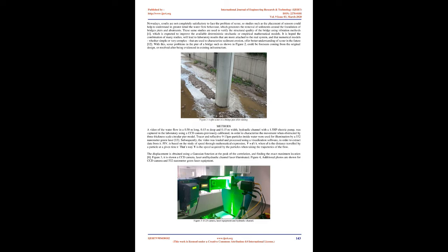Figure 1. PIV equipment and hydraulic channel. Since computers and cameras with CCD technology, charge-coupled device, were developed, it laid the foundations of this digital technology too, giving rise to high-resolution imaging 7, which is intended to deepen the understanding of the phenomenon of scour, characterizing the flow speed, its hydrodynamics, linear patterns, vorticity, and shear stress 3, 5. It is also possible to analyze the size of the sediment transportation and the depth of scour that can be generated around structures such as a bridge pier.